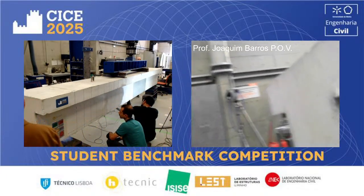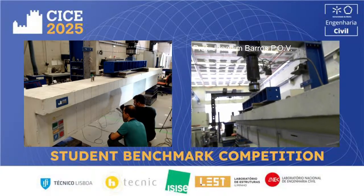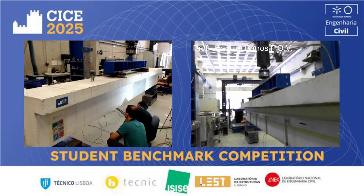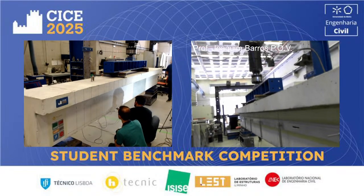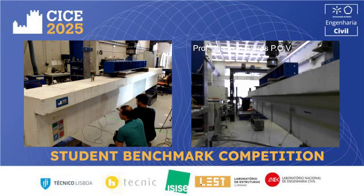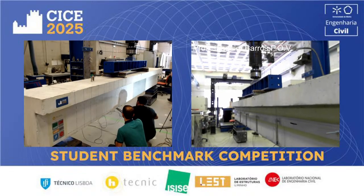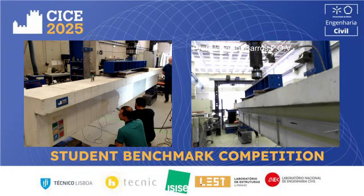Above this loading level is the contribution of the CFRP laminates, that will allow the beam to continue supporting load. We also have the collaboration of the flexural steel bars due to their hardening behavior. In this phase, as you see, we have an aluminum bar that is supporting the LVDTs. This system allows us to exclude the registering of parasitic displacement.